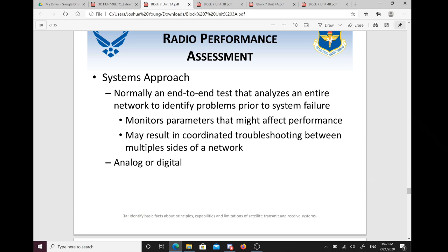So then they can determine whether or not they're even able to see or receive your signal from point to point and where you're sending your data transmission. And based on that information, well, if they can't even see us, that could only be a couple of things. And then you would use your technical order associated with whatever antenna or radio you're operating to figure out if your transmit and receive frequencies are correct. Are you applying enough power to your signal? Is your radio transmitting at all?